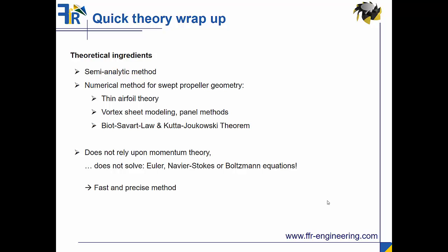So from the ingredients, as I said, we're using a semi-analytical method. So it is a numerical method for swept propeller geometry. And this is based on thin airfoil theory, vortex sheet modeling, panel methods, and applies the Biot-Savart law and the Kutta-Joukowski theory. For those of you familiar with aerodynamics and also aerospace and aircraft engineering, I think these things are quite well known. And what we don't do in this code is rely upon momentum theory, which means that we don't use or solve something like the Euler equations or Navier-Stokes equations or Boltzmann methods or lattice-Boltzmann methods or something like that.